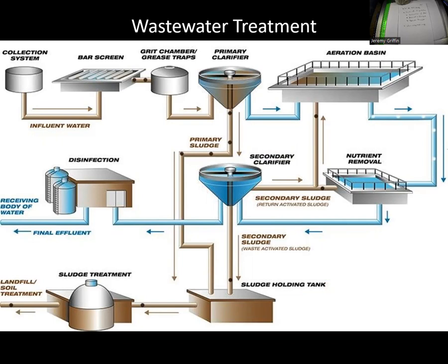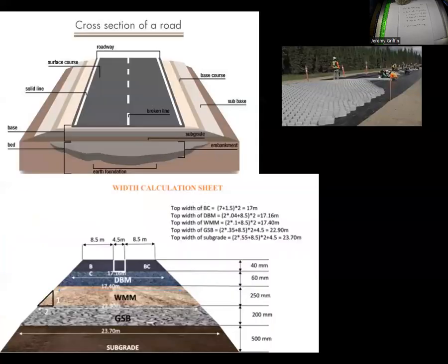And just like the clean water, this wastewater, there's different ways that you can treat it. So one method you can use is use bacteria to eat all the waste products so that when you do eventually dump the water back into the environment, it's a lot cleaner. You can also burn the waste in the water, like allow the water to evaporate and then burn what's left behind. You can allow it to ferment, capture the methane from it and burn that for energy, right? Like a waste to energy type process. And so yeah, there's lots of processes you can use, but you want to treat your water before you dump it back out into the environment.